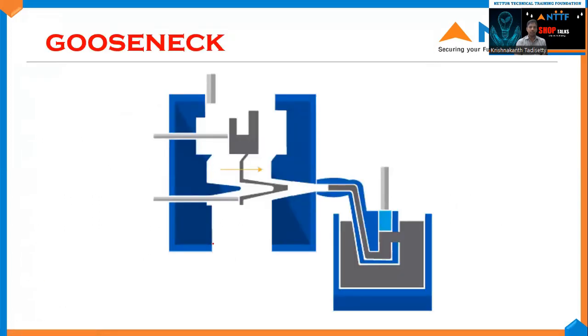In this picture, we can observe the fixed half and moving half components and also ejector pins and also the gooseneck. That is called a gooseneck because it looks like a gooseneck, and that is called a piston, which is used to make the molten material flow to the chamber. This piston has a major disadvantage: the piston is used for filling the material into the mold cavities, and in that process, there is a 100% chance of the piston wearing out.